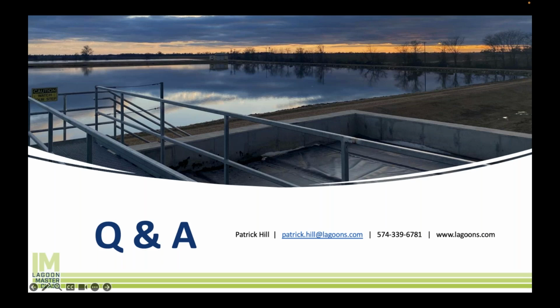Duckweed assimilates the ammonia into its cell wall when it grows, and it sits on the top, so often it's not discharged. It sucks up the ammonia, then dies off in the wintertime, sinks to the bottom, and starts to break down. As it breaks down on the bottom, it re-releases that ammonia. It's called benthic feedback, and that's classic.